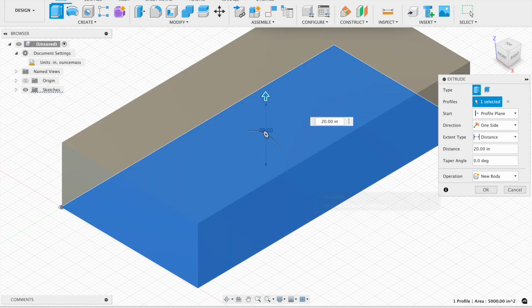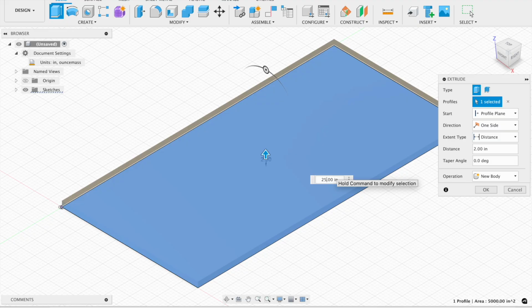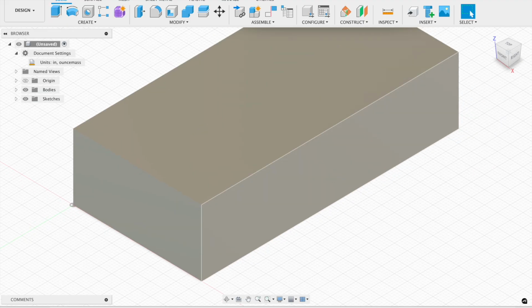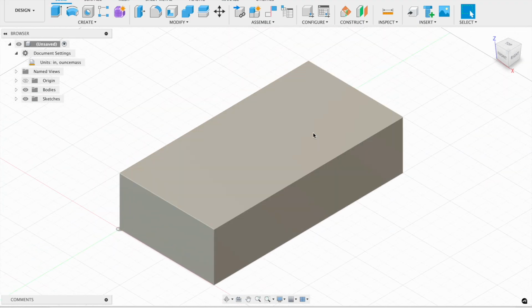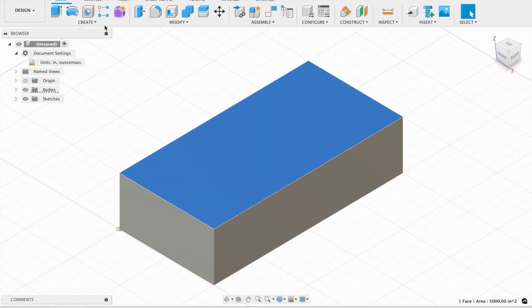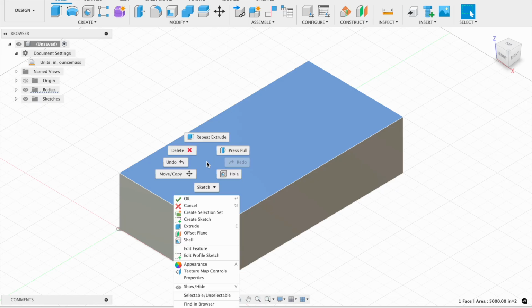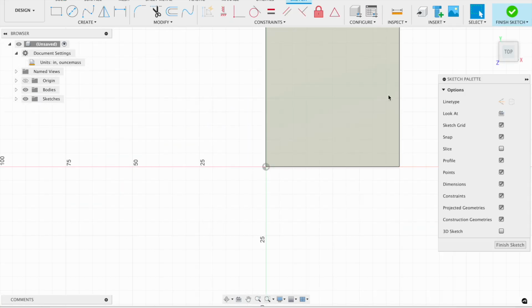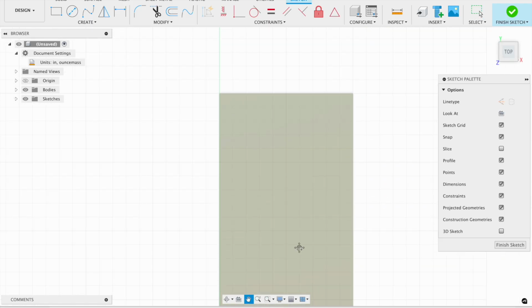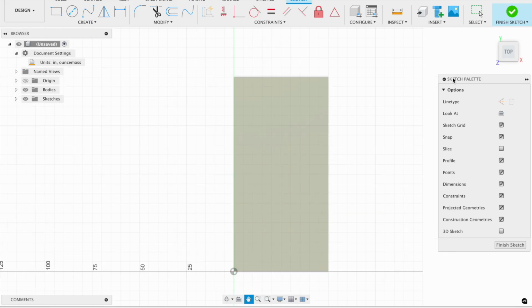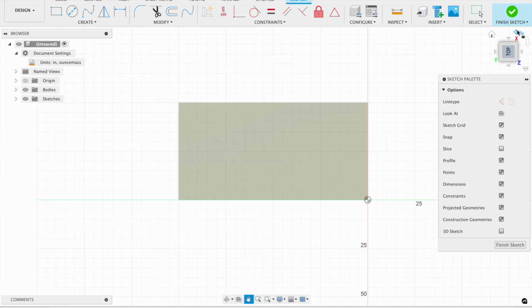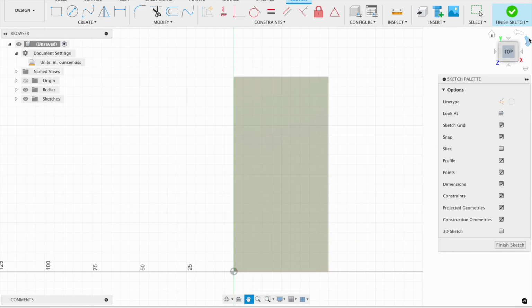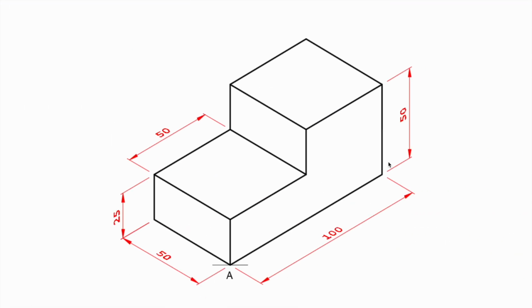And you'll see what I do next with making that extra 25 inches up, because you see that it's basically two levels. With that, I'm actually going to click that plane, and I'm going to click create a sketch. I'm going to sketch on that face, essentially. And this is where I go back to my drawing after I orient it the way I want. So you're going to see me find the perfect orientation because it needs to be a very specific way.